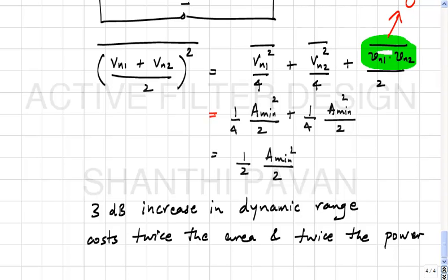So the question is, where in the passband do you put it? It turns out that a common good place is at passband edge by 3. That's a good rule of thumb. I'll tell you why this is a good rule of thumb when we get there. So the tone must be in band, and roughly at band edge by 3.